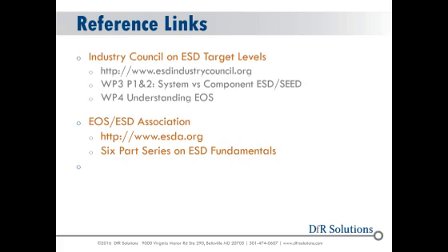That's another thing you need to think about: what is your return path, and Greg alluded to that. It doesn't matter how good your clamp is, if you're trying to funnel that energy back into a return path that's very high impedance, then you're just going to get a high voltage glitch across that. So it's a system level analysis that you have to do to put yourself in the mindset of, okay, here's the pulse coming in, here's the shape and the intensity of that pulse, where does it go, and what residual elements of that pulse enter the circuitry I'm trying to protect. So it's the same analysis all the time.